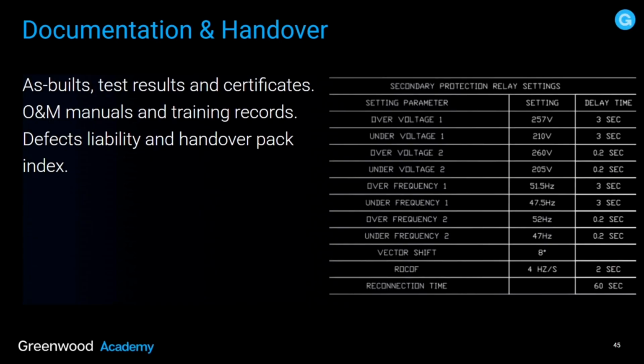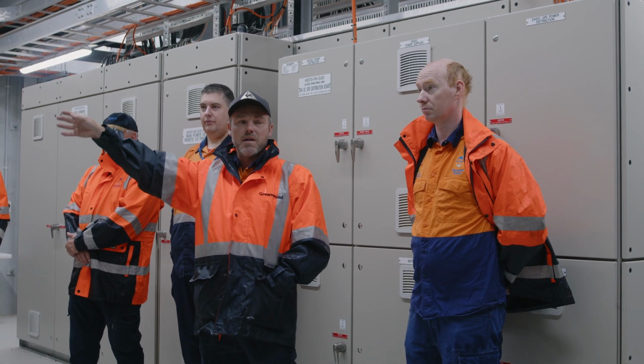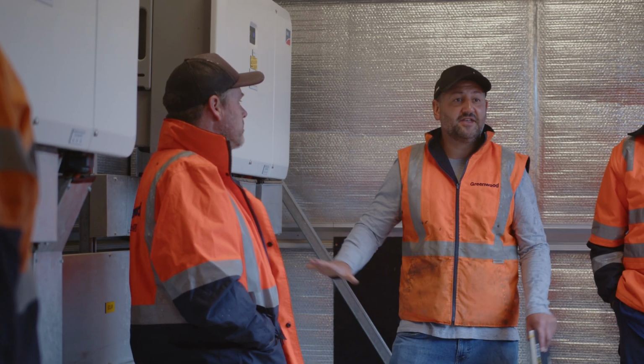Document and handover. As-built, test results and certificates, O&M manuals and training records, defects, liabilities, and handover pack index. Handover is not just a dump of documents, it's a curated pack. Include an index, verify completeness, and run training sessions for operations staff if applicable.